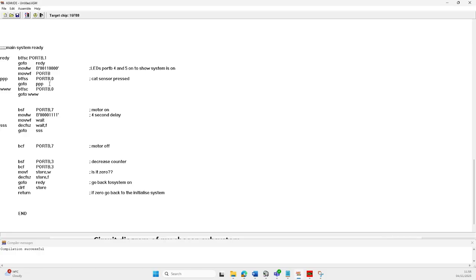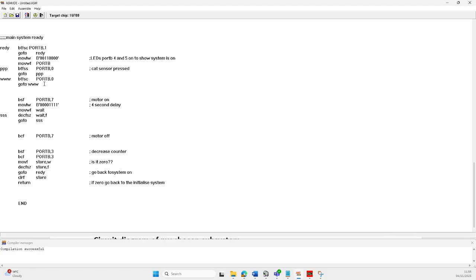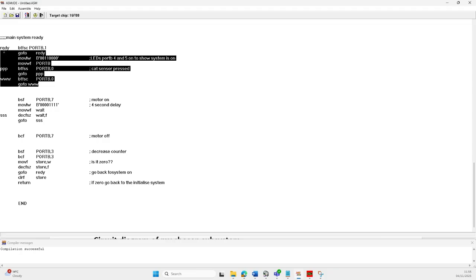So I'm just going to show you the next one here. This one here is waiting for the button to be pressed, isn't it? So again, your alternative subsystem might be a different sort of sensor. It might be, because you're using those 2 LEDs to turn on, it could be some sort of audible display. So you could maybe have a transistor with a buzzer, and you could say instead of using the LEDs turn on, I'm using a buzzer turn on to show that the system is on. Obviously, the drawback of that is the buzzer would stay on. So you can find an alternative to that.